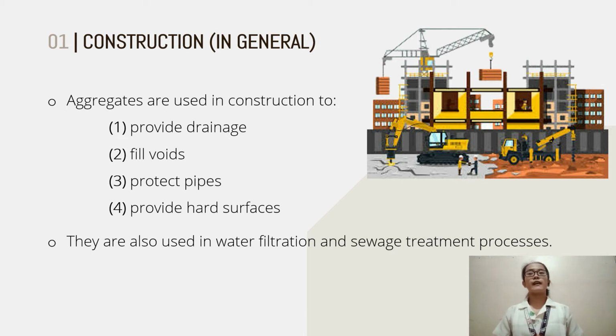And second is to fill voids. Voids created around the foundations of buildings during construction are filled with aggregate because it is easier to compact than the original soil that was removed. So this results in a more solid finish that will support the structure. And aggregates generally are not affected by the weather as much as soils, particularly clay soils, so it will not suffer from shrinkage and cracking during dry spells.